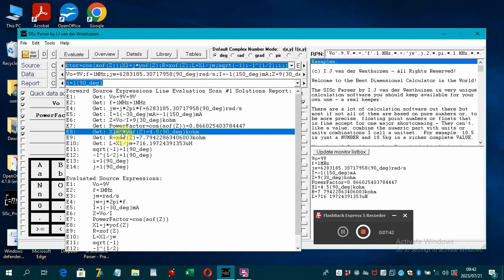Say it's on the y-axis, and then we multiply that with the y component of the impedance Z, and then we get that complex or y component, a y-axis value of 4.5 kilo ohm. If it was a negative value, with the same angle there, if there was a minus before the 4.5, it would mean that XL would have been on the negative y-axis in kilo ohm units. So we can do complex units, as you can see.